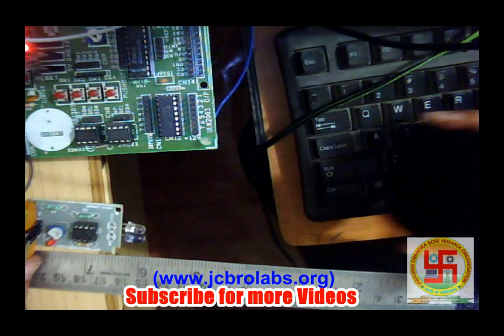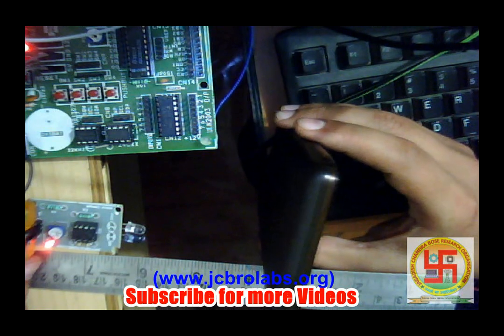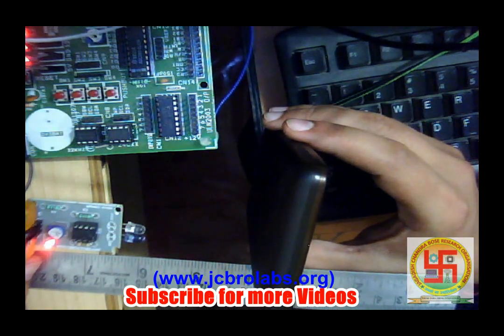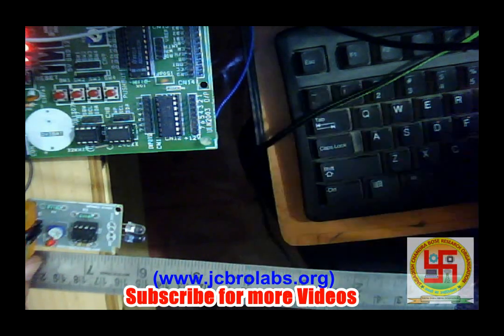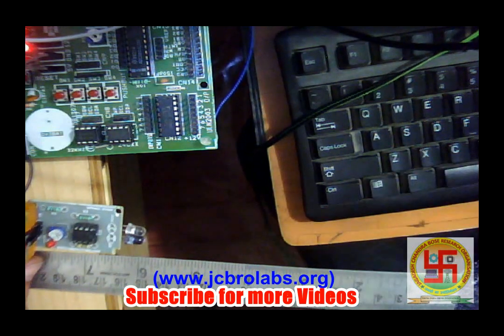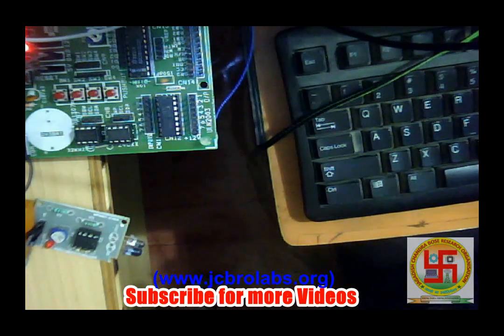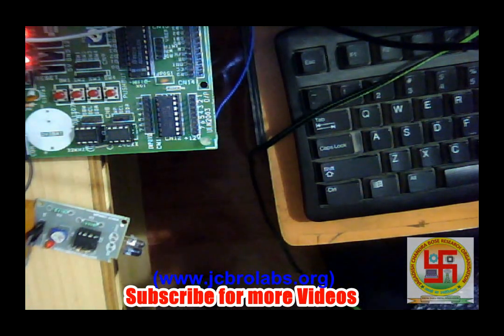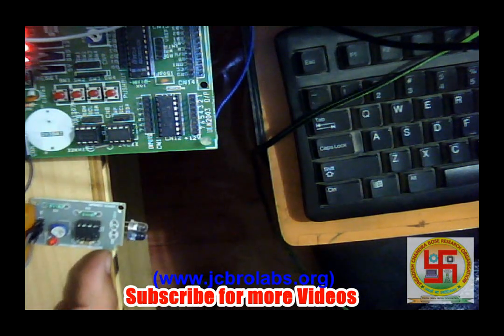So when the range is high, at that time it can even detect the black surfaces, but the range for black surfaces will be less. Right now for black surface its range is 2 centimeter, while for the white surface its range is nearly 6 centimeter. So depending on the value of the resistance we are providing, we can change the distance, and we can change its behavior with respect to the color as well. So this was a brief intro of this IR sensor and its working.